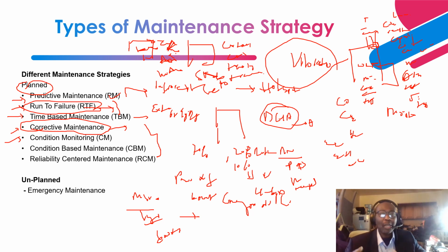And for a whole substation setup, you can also have visual and thermal cameras installed at various strategic locations within the substation environment. Based on the size of the substation, let's take an example for a bigger substation, you can have between 5 to 10 visual and thermal cameras assigned at different locations and different angles, providing hot spot temperatures for various equipment connections. So that is a typical example of condition monitoring.